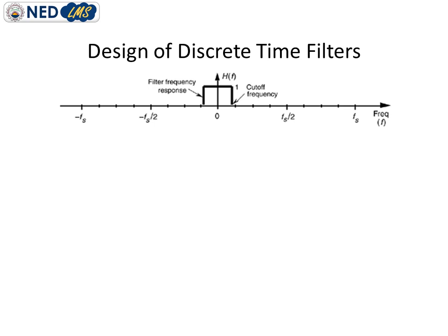and we can say that this response is of an ideal low pass filter, because an ideal low pass filter provides unity gain at the lower frequencies and zero gain at the high frequencies, or in more technical terms, a low pass filter with unity gain at low frequencies and zero gain or infinite attenuation beyond some cutoff frequency.